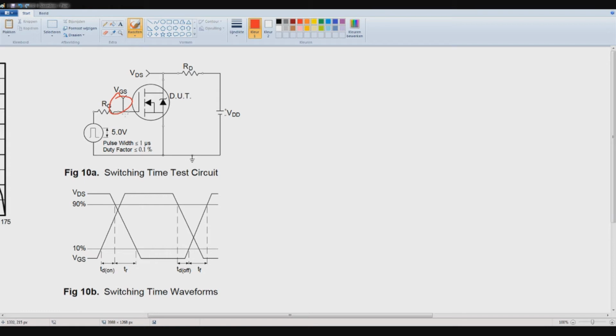This is one probe which you attach, one here and ground of course, and one probe here also to ground. Very simple. A arbitrary drain resistor so that you don't short out the MOSFET, so you can analyze this waveform that comes out of it.